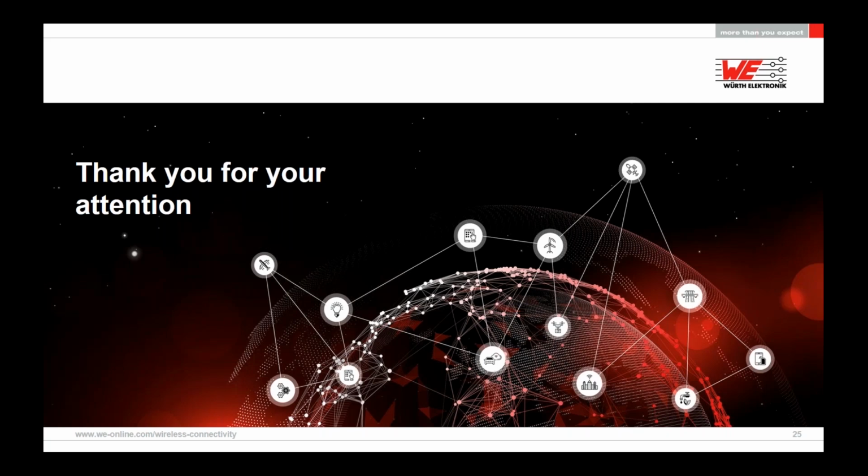Oh, of course. If you have the space, an external antenna is always better because of its characteristic. In the case of internal antennas, meaning PCB antennas or chip antennas, because of the size, the characteristic of the antenna is somehow limited, because it's not as omnidirectional as an external antenna. So you have to take care of the orientation of your end device, because the gain in a certain direction is better, and in another direction it's a bit less good. Therefore, if there is space, use an external antenna, because the gain is better, and therefore also the range. Yes. Okay, it looks like the smaller PCB antennas and so on are more directional.